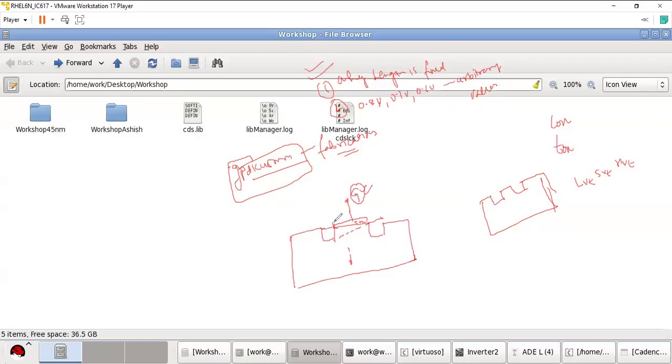If I make this SiO2 region thick, will the gate voltage required be higher? Or if I make this region thin, will the gate voltage required be higher? In case of thick SiO2 and in case of thin SiO2, in which case will the channel form early? Just guess. I repeat my question again. I have a MOSFET.